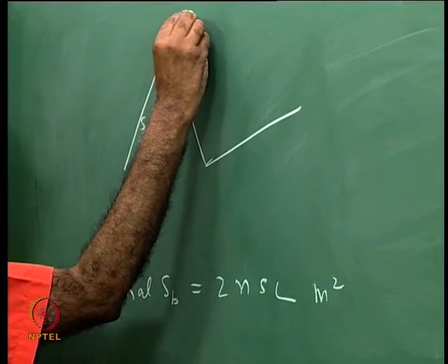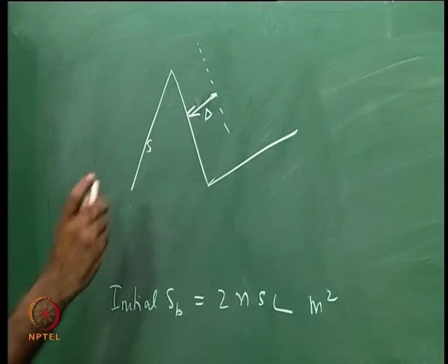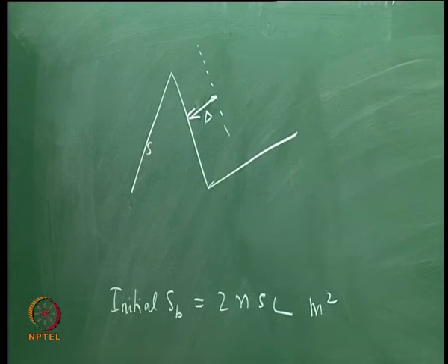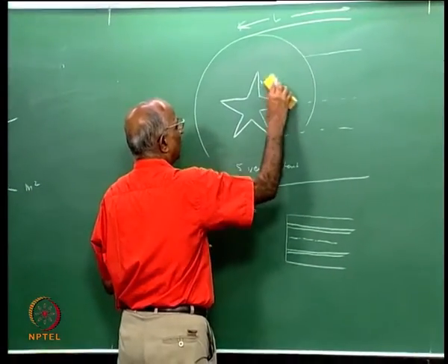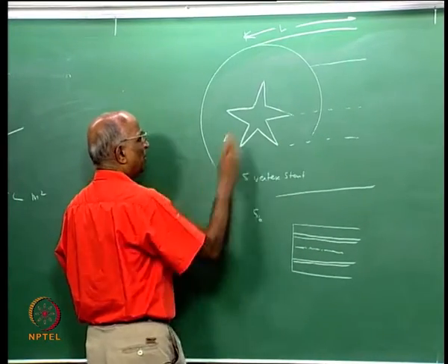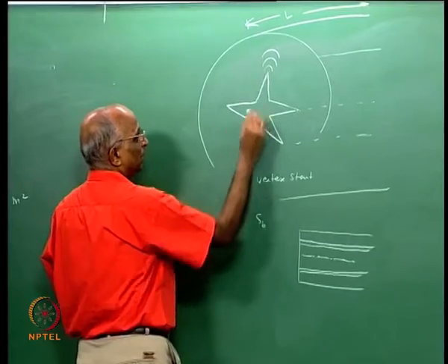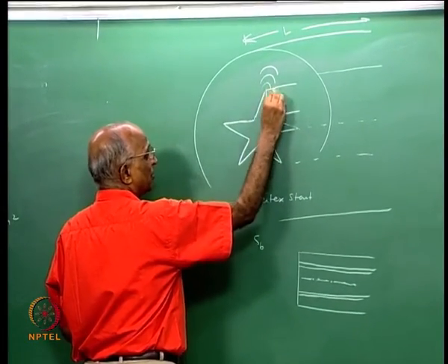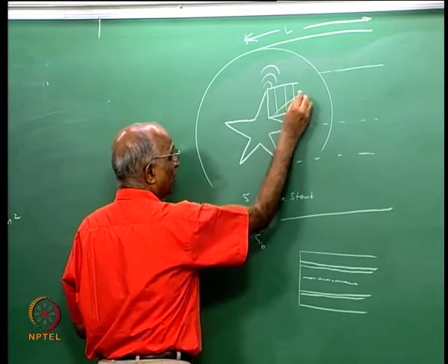Let us say the burning surface area now comes over here, it moves through a distance delta. I want to calculate what will be the configuration of this particular point. Can I choose some axis of symmetry or something and still do the problem? Let me come back to this figure, maybe it will become a little more clear. What is going to happen? We say this is a point, it will burn a circle. Here the regression will be normal to the surface, that means this surface area should come like this, but then this surface area should again go like this.